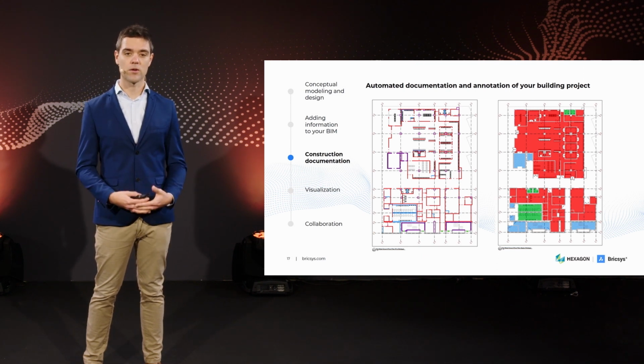2D drawings will look, including automation of tag placements and drawing customizations. Then, these automatically created sheets can be freely annotated and dimensioned using the 2D drafting tools that are available natively in DWG, while the drawing views stay in sync with the 3D model. Peter, a product manager at Bricsys, will now explain how the project browser can be used to create and manage